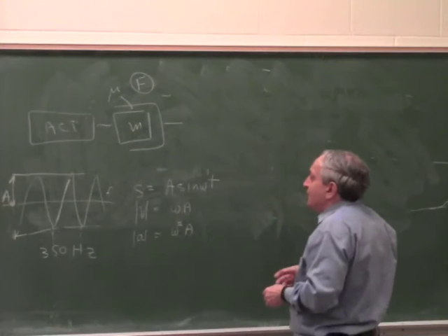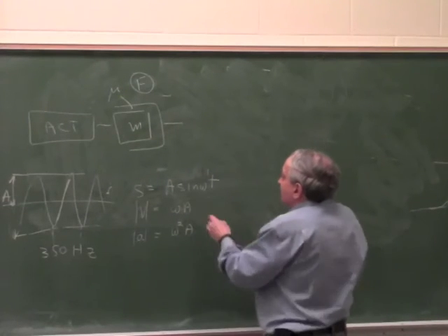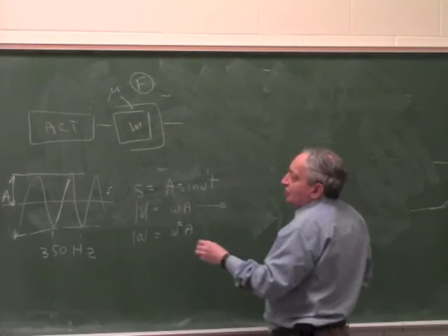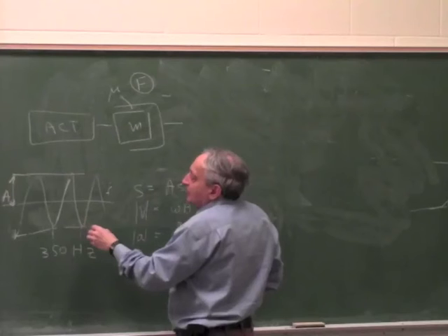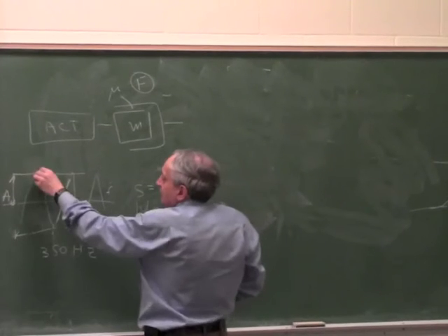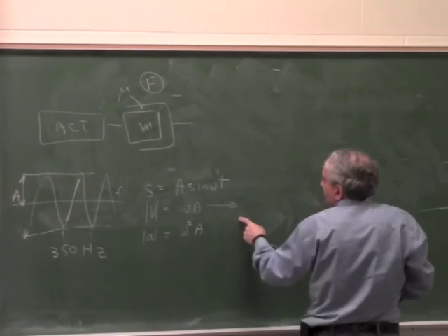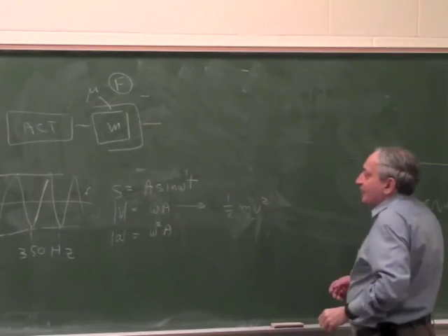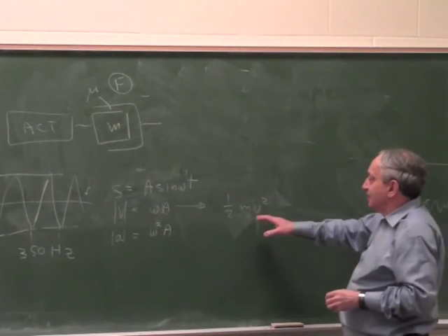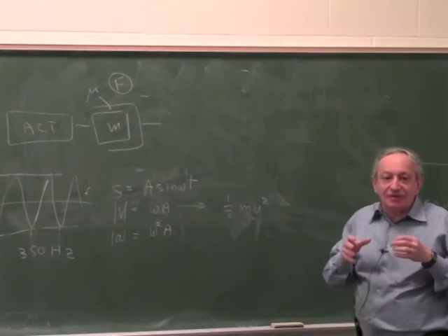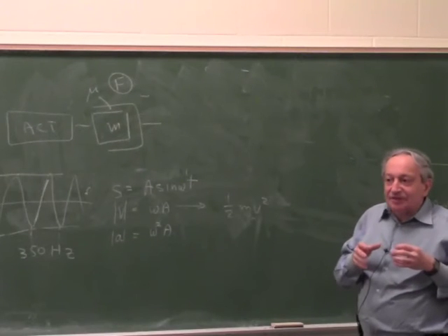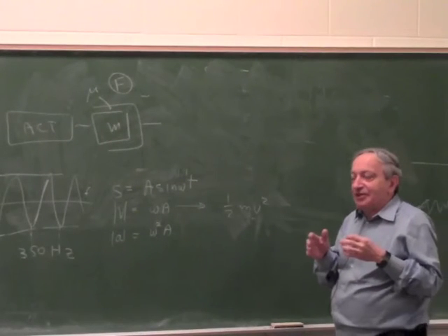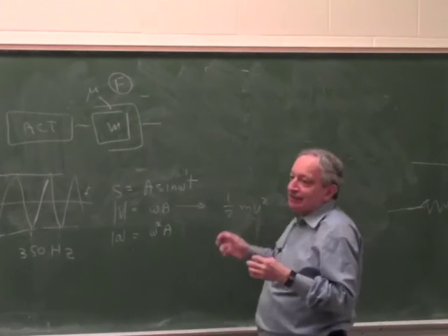Or another way of doing it, if I take the stored energy from zero velocity to maximum velocity, I'm storing an energy of 1/2 mv squared. So per cycle, this is a part wasted on inertia. Now, of course, there is a fine argument here, because this energy is recoverable.